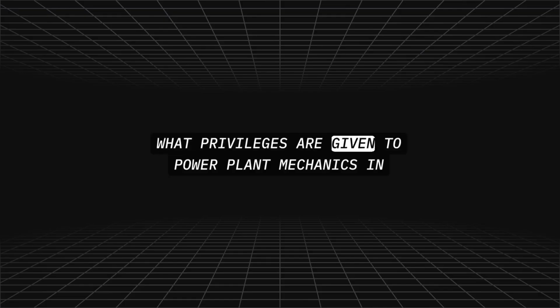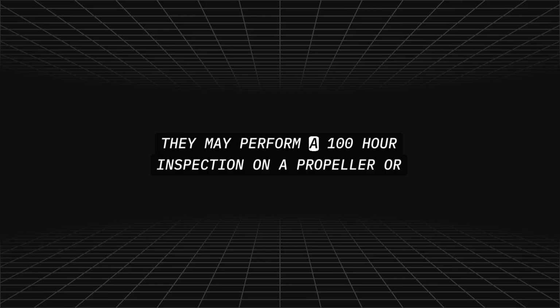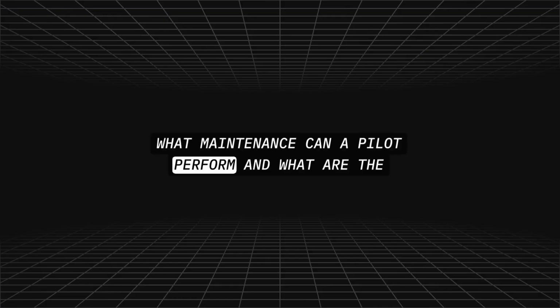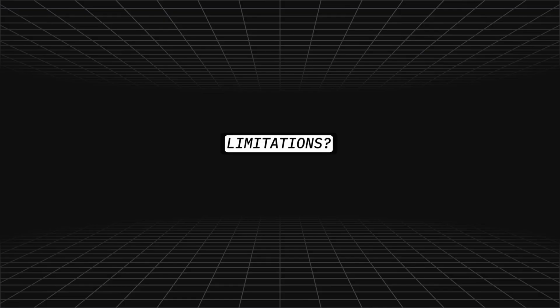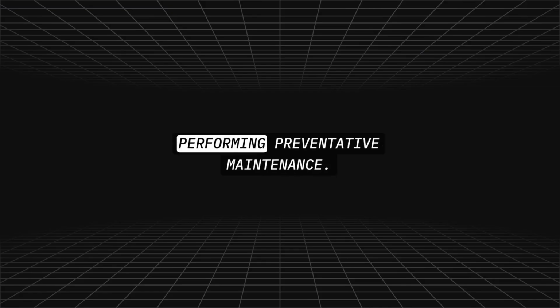What privileges are given to power plant mechanics in addition to the ability to perform maintenance? They may perform a 100-hour inspection on a propeller or engine. What maintenance can a pilot perform, and what are the limitations? They may approve an aircraft for return to service after performing preventative maintenance.